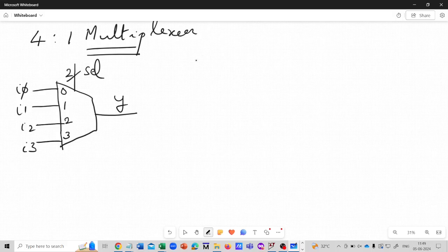So that's it. Now we will try modeling the behavior of this multiplexer. I am dispensing with the module definition because I am presuming that by this time you would have already understood how to define the module and declare the inputs. So right away we will go to the always block. The first step being to include all the input signals in the sensitivity list.